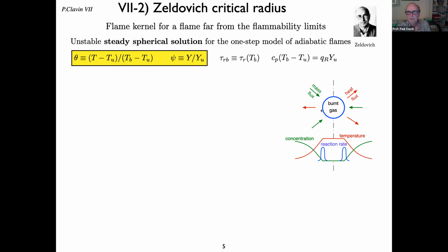So it's a premixed flame with a constant radius, standing steady, and it is fed by the diffusion of mass coming from the mixture from large radius, and the heat being extracted from the flame, from the reaction rate, by the diffusion. It turns out that in spherical geometry, this equilibrium is not possible without motion of the flame front. This was realized by Zeldovich during the 1950s, I guess, something like that.